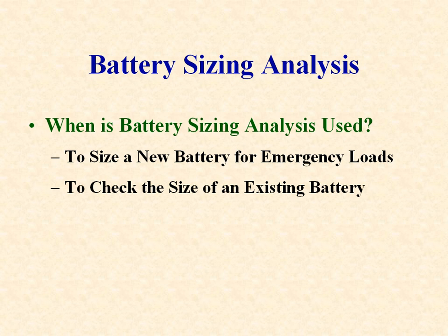The battery sizing module is used to determine the size of a new battery for a DC system that needs battery backup. The sizing analysis can also be used to check if an existing battery is adequate after changes have been made to the system loads.